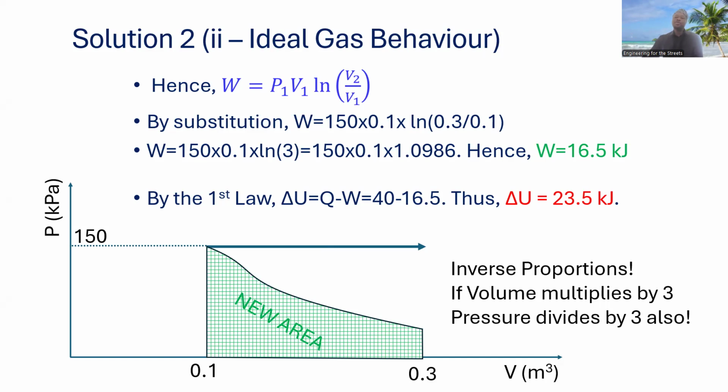For instance, a motor might maintain the gas in the piston at constant pressure while the piston is expanding. So you need an external force to do that, and to overcome that external force, you need more work. And that's why the work done at constant pressure is higher than the work done under normal ideal gas behavior.